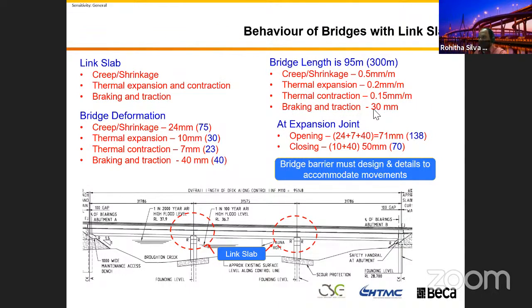And then the braking and traction due to traffic will be acting, because this bridge is sitting on elastomeric bearing. It's like a flat plate. It will move in one direction at about 40 millimeter. I just put this one right in here.